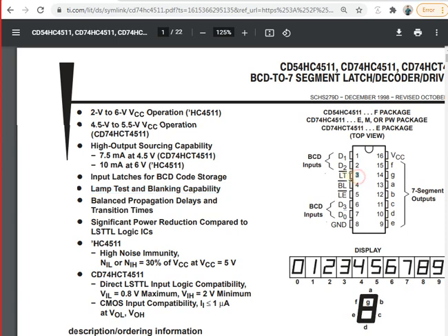What does LT mean over here? This third pin, LT, means lamp test. So sometimes when you are debugging and you want to test it, you can test out your IC. And the blanking capability: BL stands for blanking capability. So you can actually blank whatever you are displaying over there.